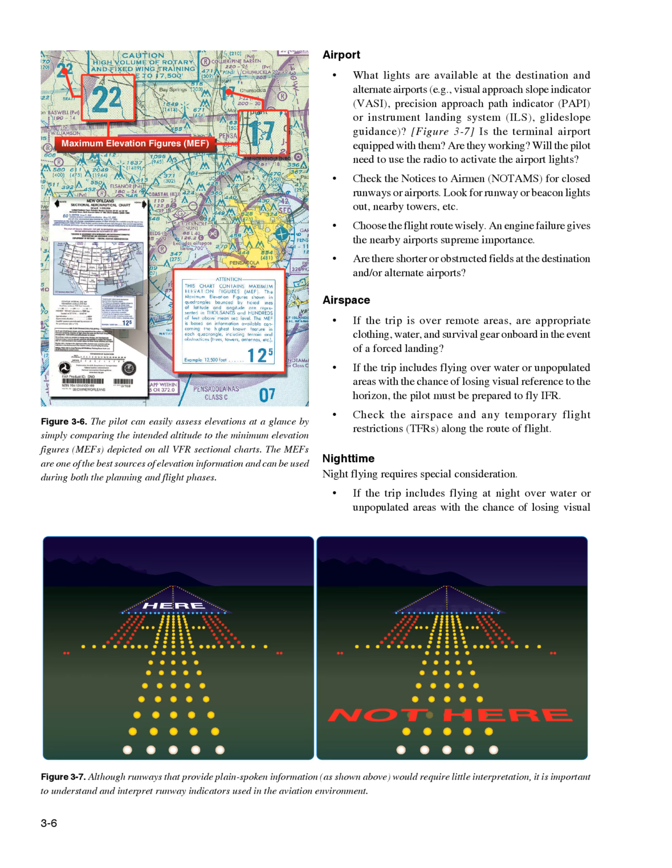Check the notices to airmen, NOTAMs, for closed runways or airports. Look for runway or beacon lights out, nearby towers, etc. Choose the flight route wisely. An engine failure gives the nearby airport supreme importance. Are there shorter or obstructed fields at the destination and/or alternate airports?